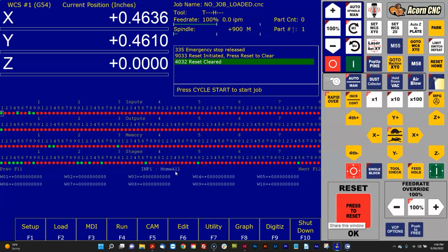So I'm cycling through the various states. I can manually invert an input. I can manually activate an output. So here, let's go turn the spindle cooling fan on. Control-Alt-F. There it is, forced on, forced off. There we are, back to normal. Do it again. And I'm just hitting Control-Alt-F to cycle through, just like in the Simplified PLC app.